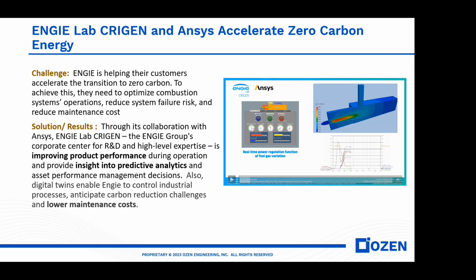So in this case, what we are doing is we are looking at a hydrogen combustion system, and the digital twin should tell me what the exhaust gas composition is like, how much NOx it is generating, how much SOx it is generating, so nitrogen oxide and sulfur oxide. And if I change some input parameter, in this case how much fuel I'm injecting, what will be my flame length? And it can also compute what the heat distribution will be like. So this is a very good example of a simple reduced order model and how it can be used in